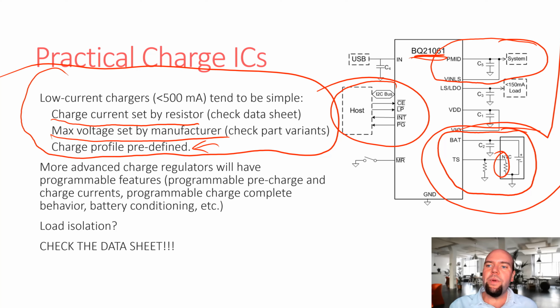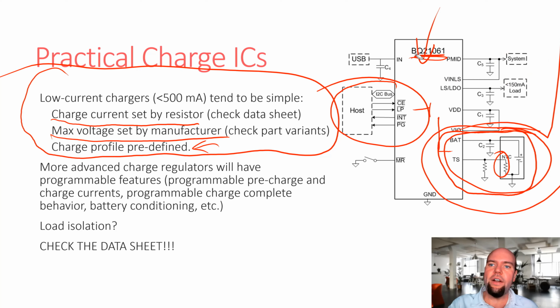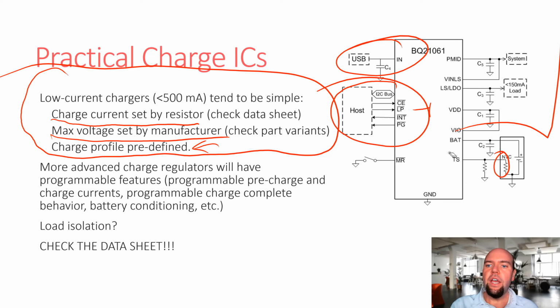But something like this, where the battery is isolated from the load, and inside here, there is a gate. So this system can intelligently, if it knows I don't have enough current coming in to power the load, turn on that gate and say, all right, I'm going to let the battery give some current to the output load, because while I'm charging, I don't have enough input current to handle what the load is trying to draw. But that's an important thing to note.